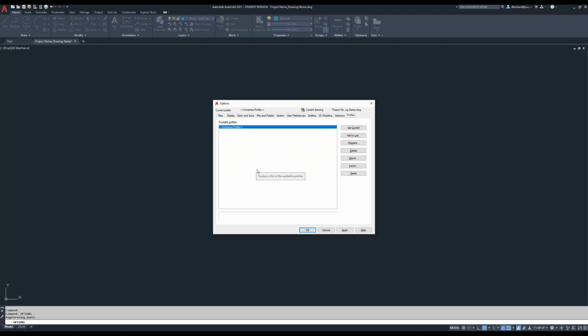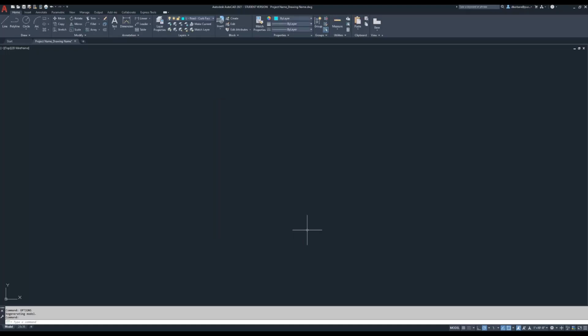And lastly, under Profiles, if you are going to be moving to multiple computers, if you want AutoCAD on your home computer, for example, or you work in a design office where you move to different machines often, you may want to save all of these commands, options, and preferences that we just set into a file that you can take with you and then import with a couple of mouse clicks instead of changing every option every time you go to a new machine. I'm not going to do that here. I'll just hit OK. At this point, we're done and we're ready to begin drafting.